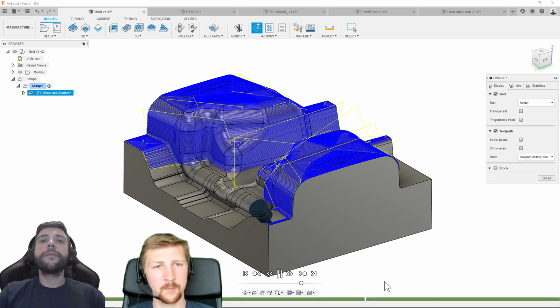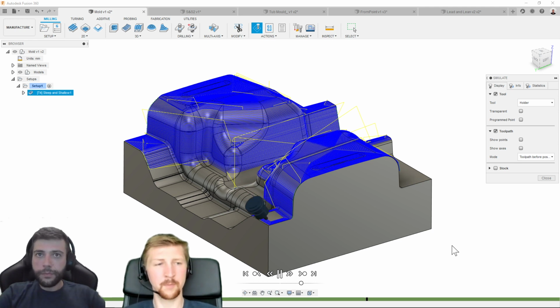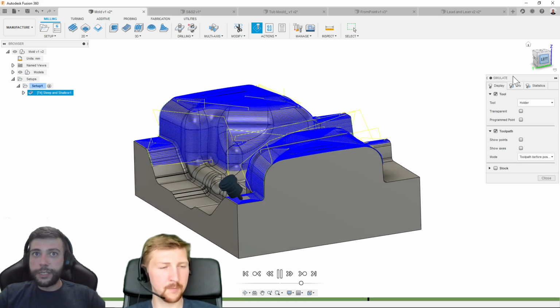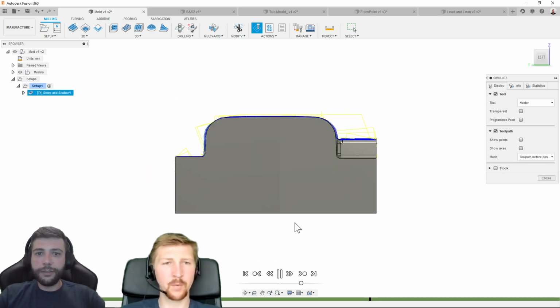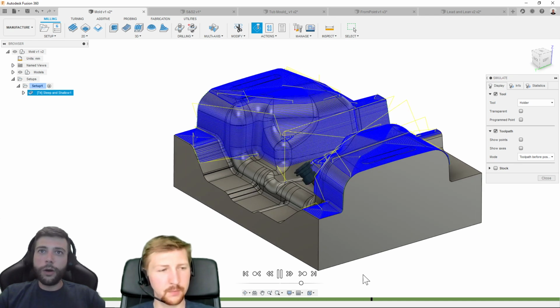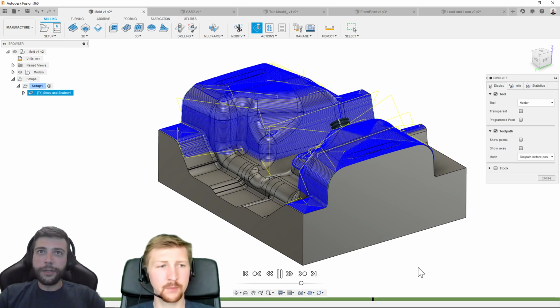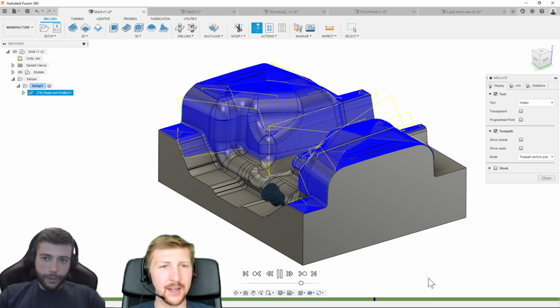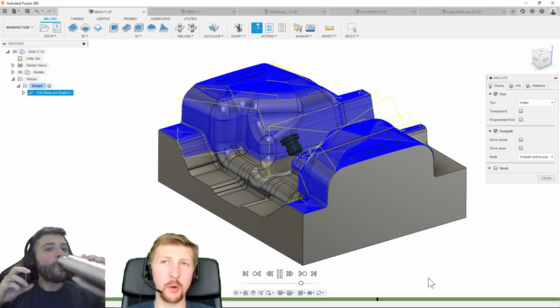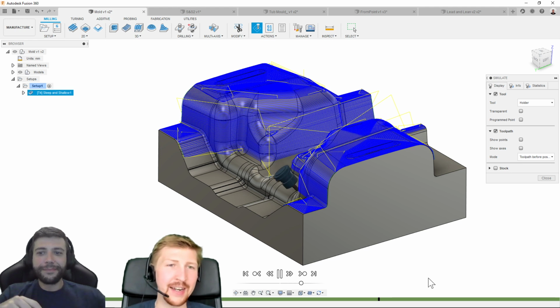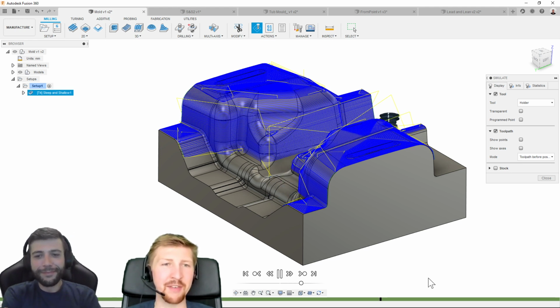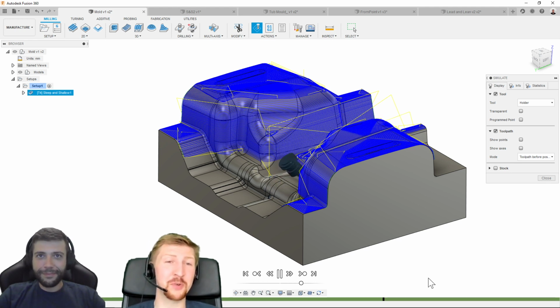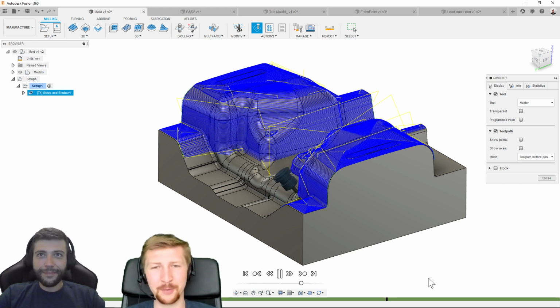See another section. Again, that way we would have risked collision with that wall if we stayed vertical. So the tool has decided, you know what, I'm going to tilt, I'm going to stay at that angle. There is just how short that tool is. Exactly. I know how many times I've gone like, "Ooh, I know I shouldn't stick the tool out this far, but I need to make the part, and I haven't got the time to start making 50 toolpaths on it." Look how short that tool is. Exactly. So your finish is going to be brilliant because the tool is so short, and low vibration. Paolo, you've made my day.